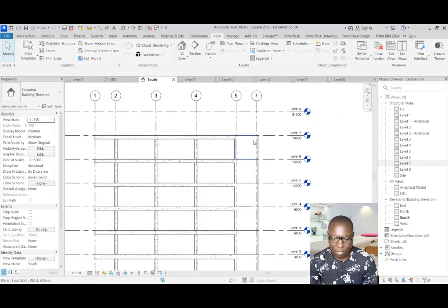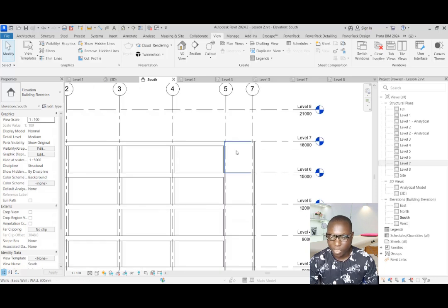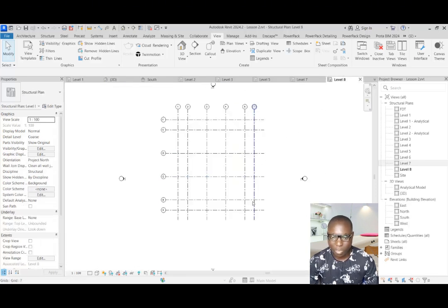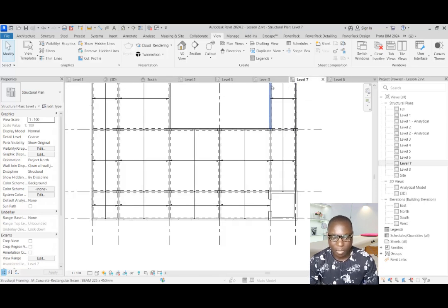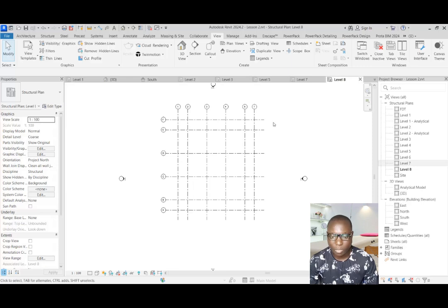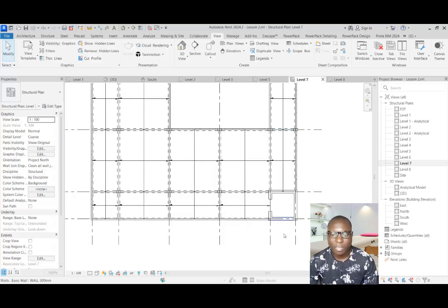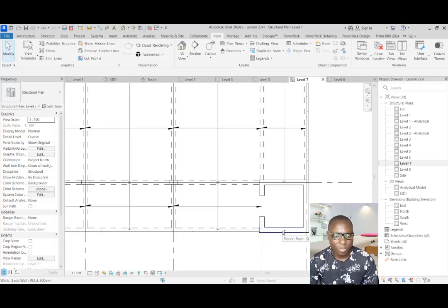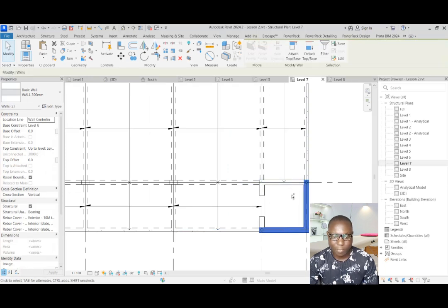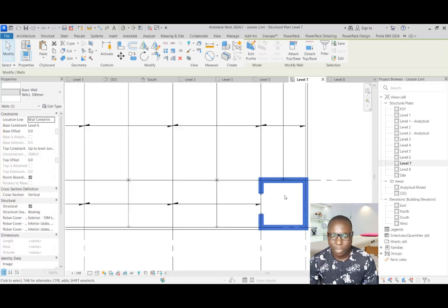Okay, so you can rename the level as well. This is showing us 9, so we can just call this 8 right here. Click in these provisions. Would you like to rename corresponding level? Yes, options. Have it as 8 right here. All right, just like this. So now we can proceed to generate the lift well. So we go back to the level 8.